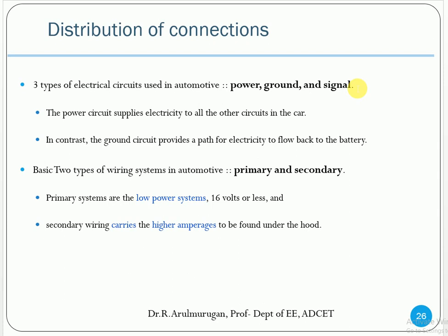Similarly, in a BLDC motor, you have seen that there are 2 parts of the wire coming from the motor. One is a power wire. High power is needed, like for operating the coil, the voltage is needed. And second one is a thin wire, that is the signal wire. Signal wire from the sensor, Hall effect sensor. Okay. And another one is a ground terminal. Ground or negative terminals. Negative terminals are common.